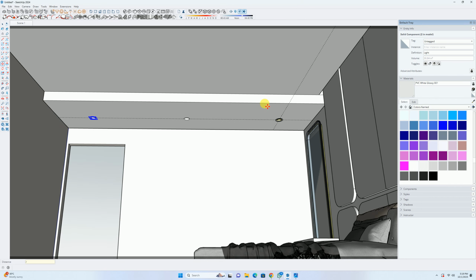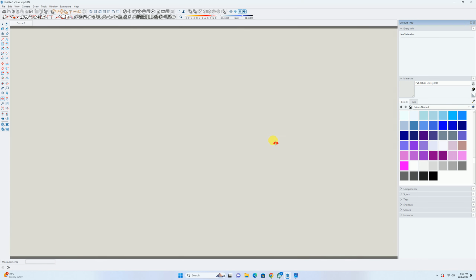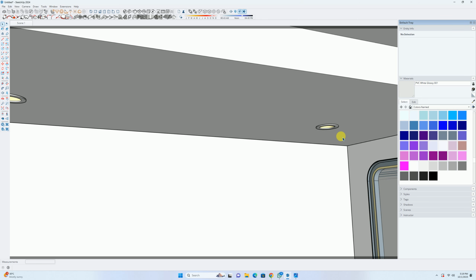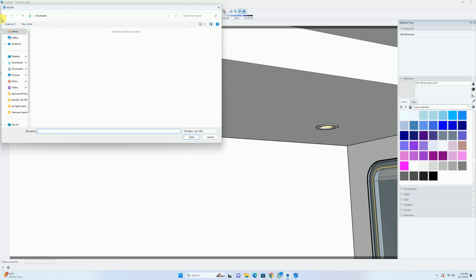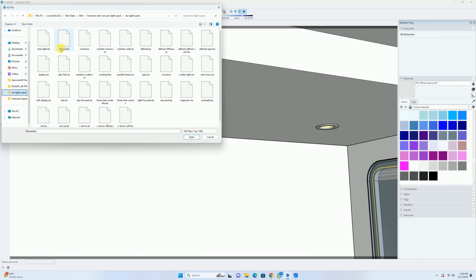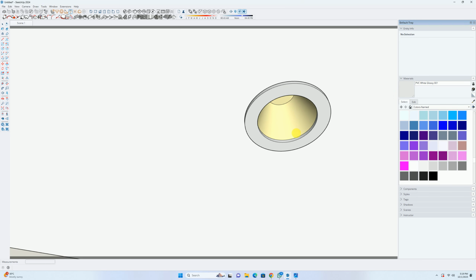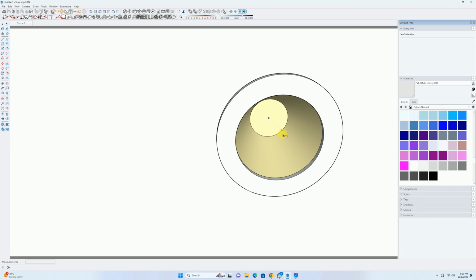Then apply slash and click. Oh, sorry. And I'll copy this at 5 feet 6 inches. Okay, because we have created it as a component, right? So what we can do here is use the IES light feature, and from over here we can select our desired IES light, whichever light we feel like. Suppose I'm using soft display light, so I'll specify the point at the center of this light.